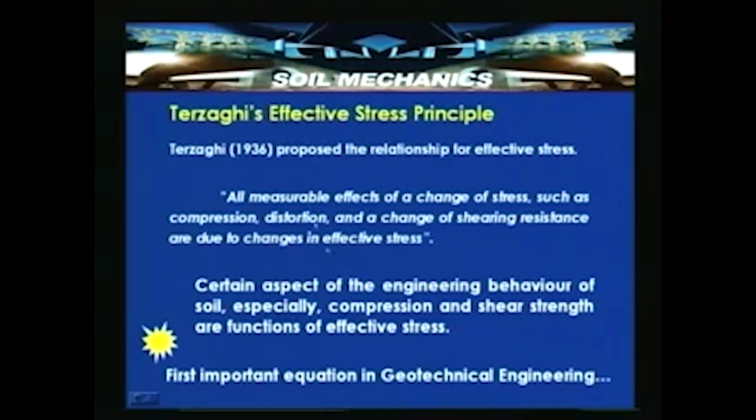Certain aspects of the engineering behavior of soil, especially compression and shear strength, are functions of effective stress. If there is any change in effective stress, it affects the shear strength characteristics as well as the compression characteristics of a soil. So this is the first important equation in geotechnical engineering. We have introduced Terzaghi's effective stress principle, and now we are looking into more detail about this concept of effective stress.